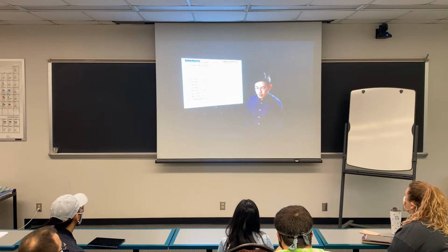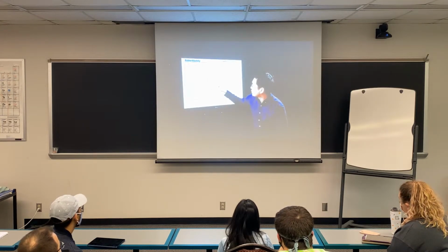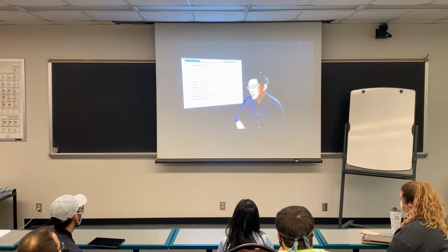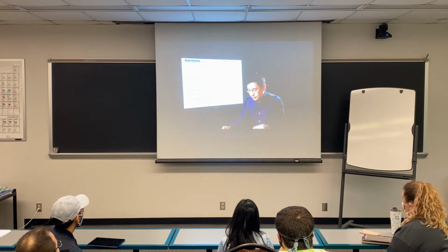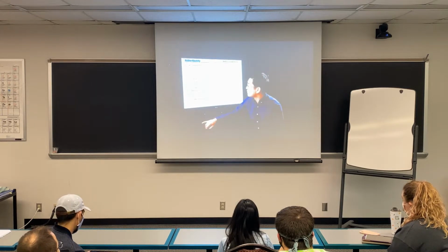So a couple of assumptions: there is no change in the internal energy at constant temperature T and pressure P, and there is no change in volume at constant T and P. And this is one of the reasons we can link the force to the partial derivative of the Gibbs free energy G with respect to displacement L.